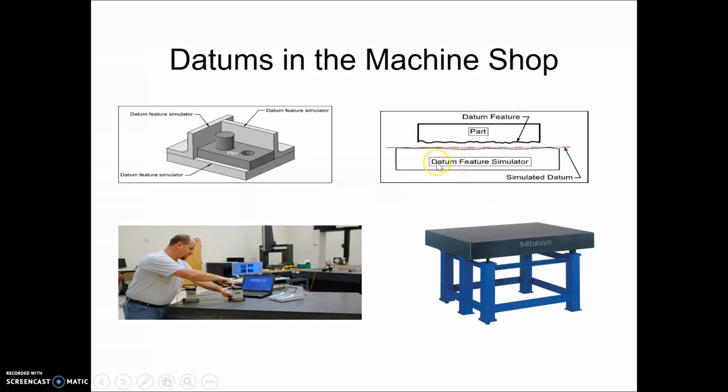So the datum simulator was what I just mentioned to you a moment ago. Notice that since flatness is in essence theoretical, we do our best to achieve as much flatness as possible so that we get most accurate results. If you notice in this case, let's say that we have a fixture here and we're going to gauge a part's tolerances and see if acceptable tolerances have been met by using this datum frame here.